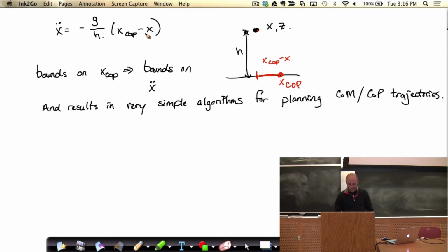Okay? So the problem of the satellite, where we have to decide when to move things around, is scary and hard and has this discrete component, it has all these other components. But somehow, if things are all in the plane, that's the only simplification we've made so far, where center of mass height stays constant and our contact points are all in the plane, then I'm going to have a very simple algorithm pop out. All right, so here's the most common way to do it. There's lots of ways you could potentially constrain one or the other, but here's a very standard way to do it.